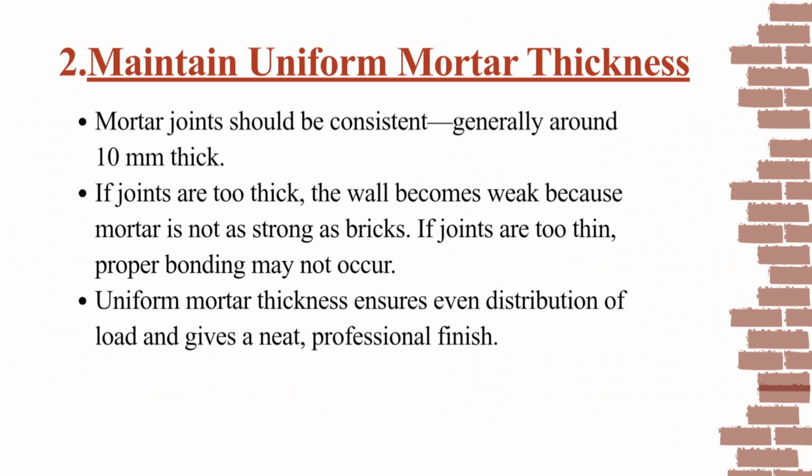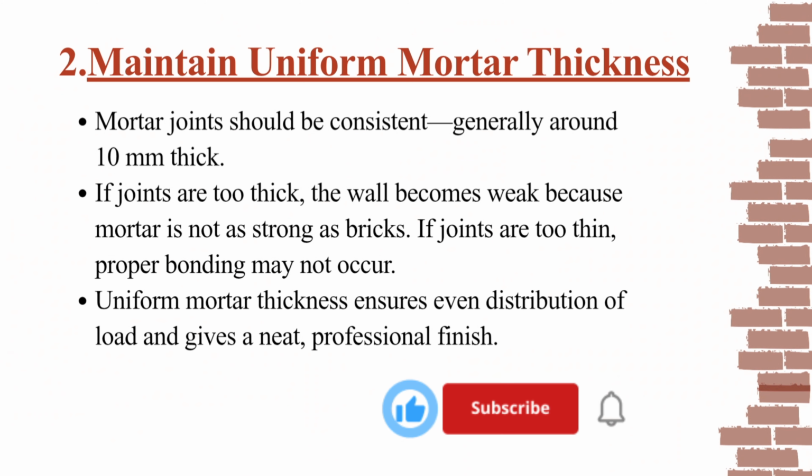And that's why uniform mortar thickness ensures even distribution of load and gives a neat professional finish. And uneven joints also spoil the appearance and make plastering difficult. So maintaining uniform mortar thickness is also an important point.